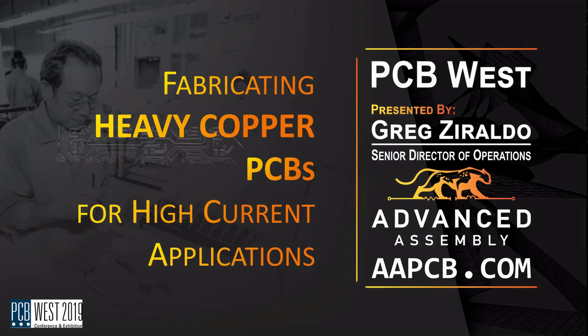These work great for a multitude of different industries and different types of designs, because we can change that profile to do a quicker and higher pre-soak prior to the reflow point. That way, from a thermal standpoint, you're not putting too much initial thermal stress on the board when it goes through the reflow zone. The other thing we have available is what is referred to as vapor phase reflow, which is not nitrogen reflow. There are a few manufacturers out there that use it, but we use it regularly and we love it.